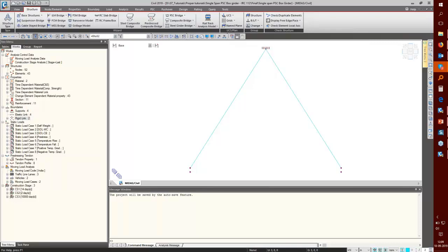Yes, so one practical limitation explained by Engineer Jatindra is that for various loads such as SLS and ULS, the axial load is varying in each case. So one stiffness will not work. That is right.